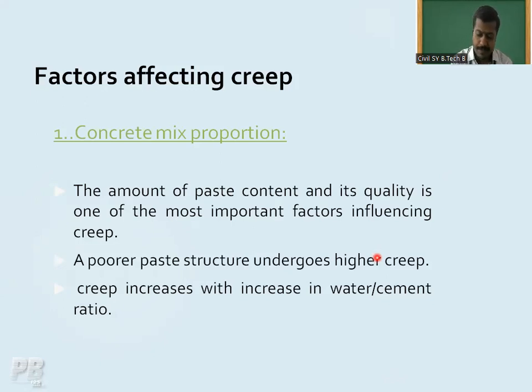Again, take this part into consideration: water to cement ratio. In every unit, I am repeating this particular word at least more than 10 times. Why is it important for us to have knowledge of it? Because in your concrete, whatever is going to happen, it may be the segregation, the bleeding, the creep, the shrinkage, or any fault or deformation of the concrete, water cement ratio always plays an important role.